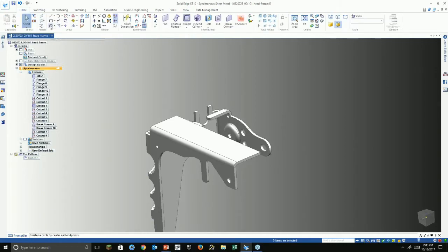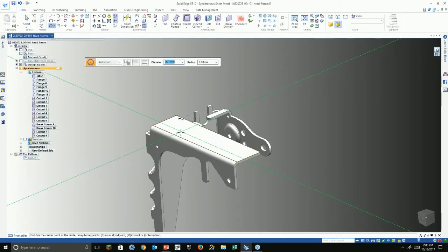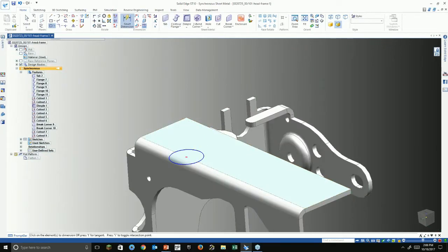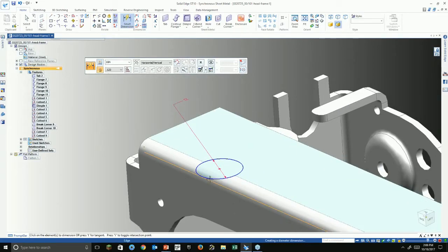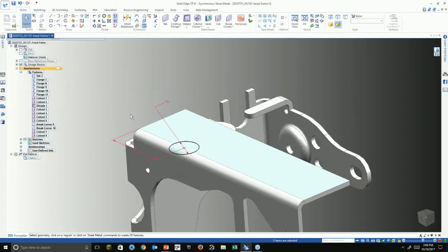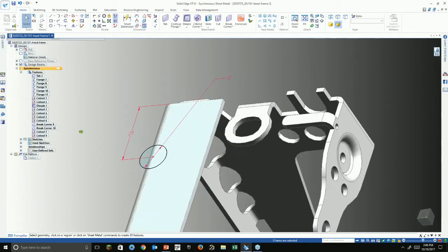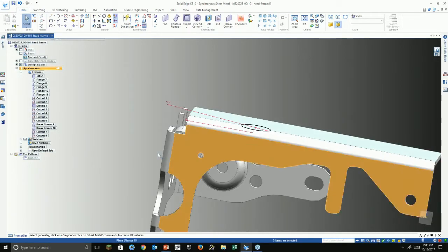It's a simple step. Just draw your profile. I'm just going to tie to that base right there. Give it the size you would like, 12, and position it from a location that you can change. Center to the edge here. That works right there.